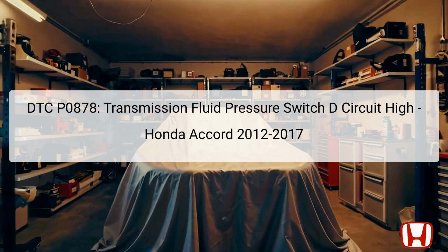DTC P0878 indicates a malfunction related to the transmission fluid pressure switch D, which corresponds to the fifth clutch in Honda Accord models between 2012 and 2017. This error suggests that the circuit is experiencing high voltage, resulting in a fail-safe condition where the transmission will only allow shifting between second to fifth gears.